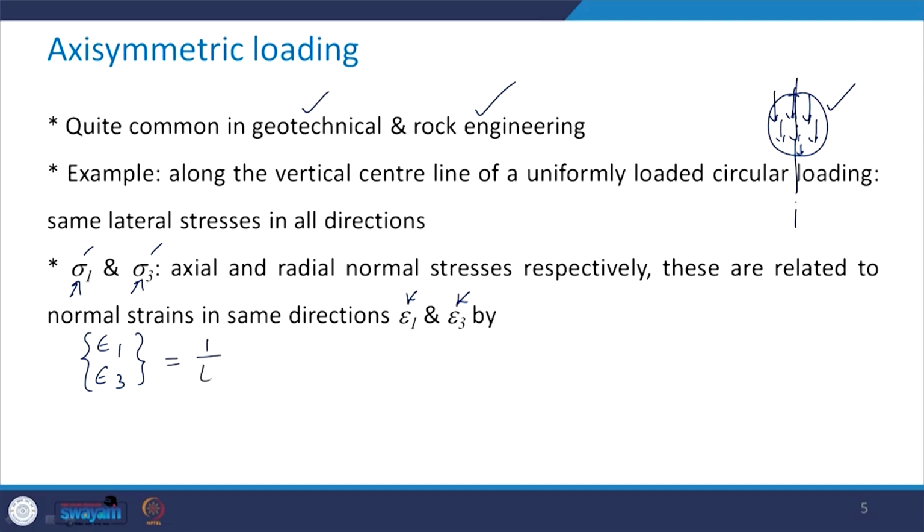That is given as 1 upon E, matrix 1 minus 2 nu, minus nu, 1 minus nu, multiplied by the stress vector, which is sigma 1 and sigma 3.